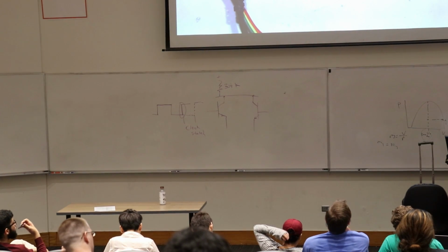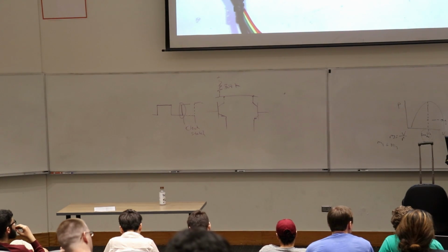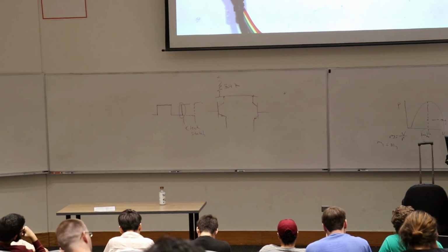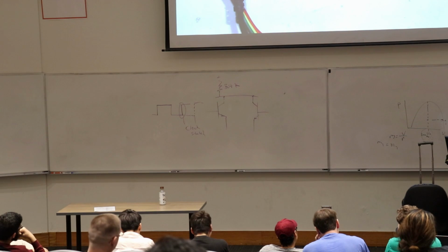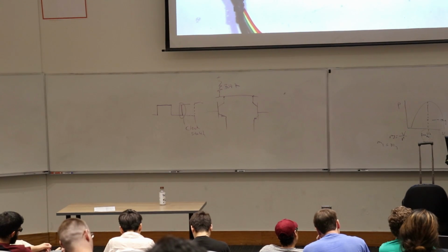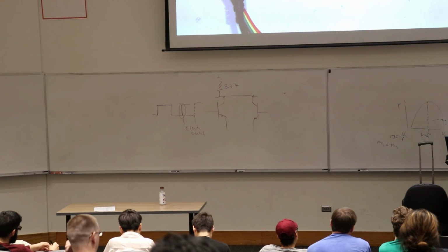Even if they've had the exact same bit pattern for a little bit, eventually there'd be a difference in the bits, and then one master is supposed to release, stop transmitting, and let the other master take over. And that's how they can have multi-master support. And it's limited. It's maybe not as robust as it could be, I guess.